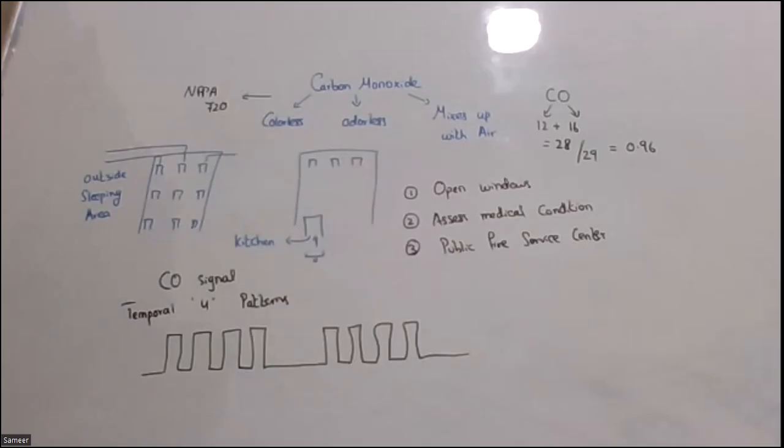For example, usually whenever a fire alarm system is being tested, the first important thing that we test is the batteries of the fire alarm system, because whenever the primary power is cut off... this is from the NFPA in the Fire Protection Handbook. They have gone to a different section. They have described the same parameters but in certain paragraphs. Other than that, they have already moved on towards failure and probability, which is not part of the examination.